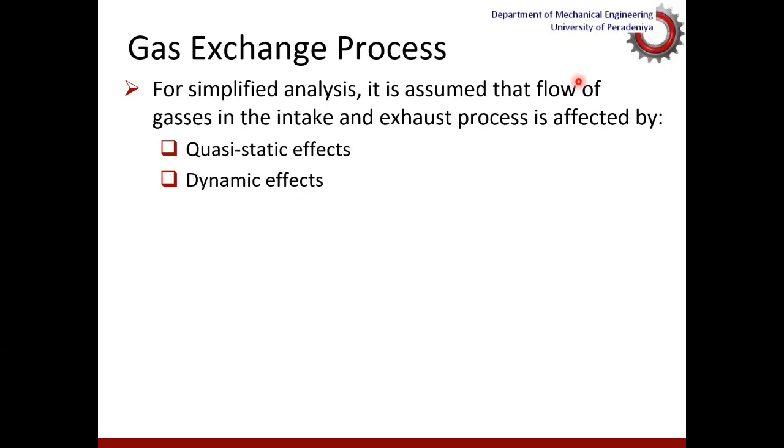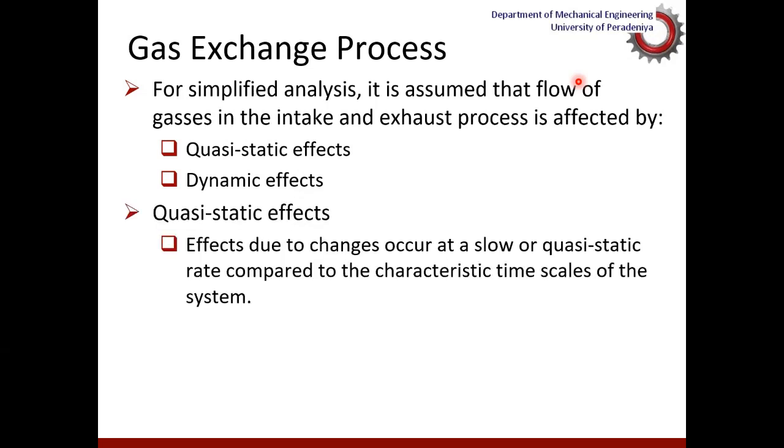Now, for simplified analysis, we could assume that the flow in the intake and exhaust process is affected by two different scenarios. One is quasi-static effects, and the other is dynamic effects. The quasi-static effects are the things which change at a slow rate compared to the characteristic time scale of the system. The characteristic time scale of the system is more or less the time per one cycle.